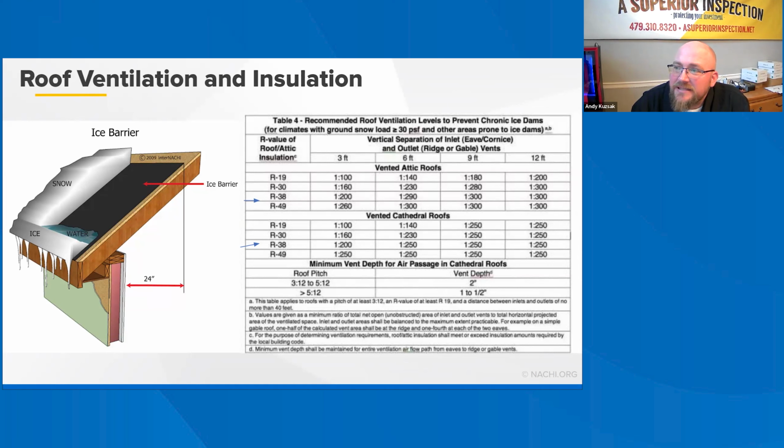Ventilation of attic areas is intended to prevent the accumulation of moisture vapor in the attic roof space and to dry low levels of condensation that may form on the underside of a roof deck. Ventilation is also intended to reduce the temperature of the roof deck during hot weather to improve shingle durability. Reducing the attic's temperature through ventilation and insulation also improves energy efficiency during hot periods.